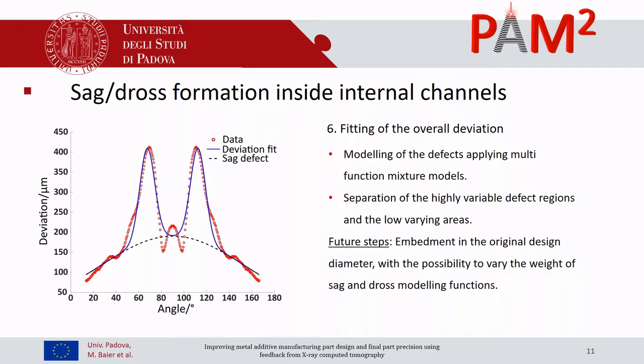But would you remove the support structure? I think it's related to the earlier question. Yeah, in this case, you would remove the support structure. So it would actually sink down, but the idea is to let it sink down in a way that it resembles the initially expected shape, which was circular in this case. So we want to deform the starting form to arrive at the desired form, which is a circle. But you're right, you would remove the self-supporting nature.